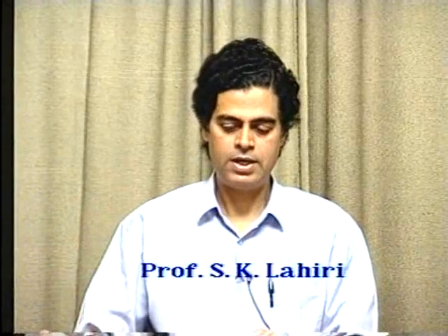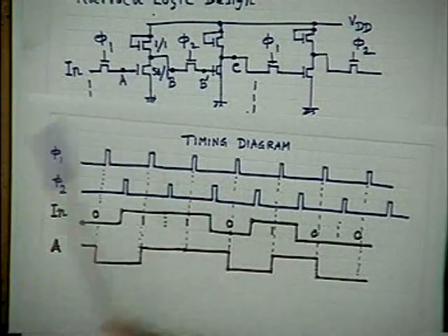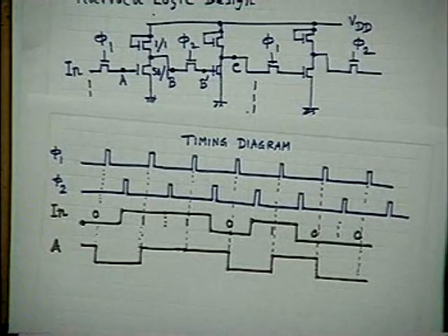Of course, I am speaking of medium advanced bipolar, not very advanced. But compared to MOS, as soon as you consider dynamic logic, the material should have very few traps inside. This should be kept in mind. There is nothing great in it, only things to keep in mind. That is why it is not only the MOS capacitance but also the junction leakage, both are important in order that it is a very good dynamic logic. Please remember this.